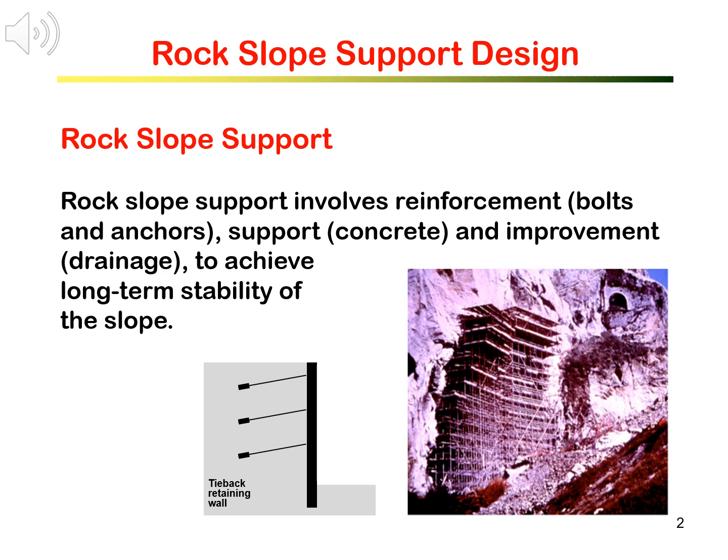Rock support can be generally classified into three categories: reinforcement of rock mass of the slope, structural support to the slope, and the improvement of rock mass of the slope. Reinforcement is to strengthen the rock mass of the slope so that the rock mass can stand and be stable. Structural support is to use retaining structure to support the slope. As we mentioned before, water pressure behind the slope is a negative factor for slope stability. Therefore, providing a drainage to drain the water away in the slope is one of the methods improving the slope.